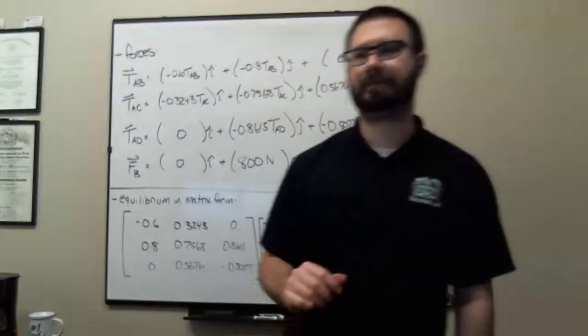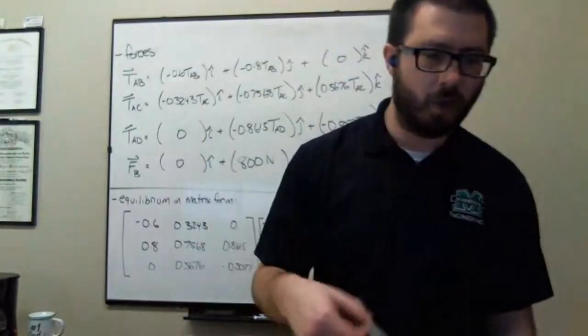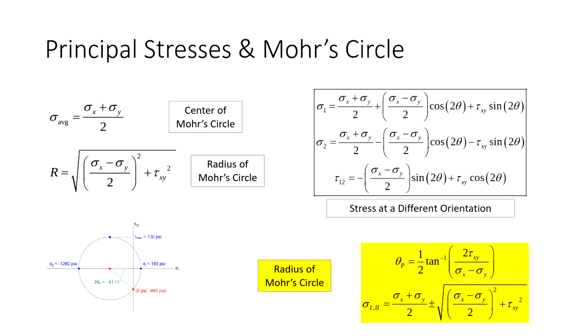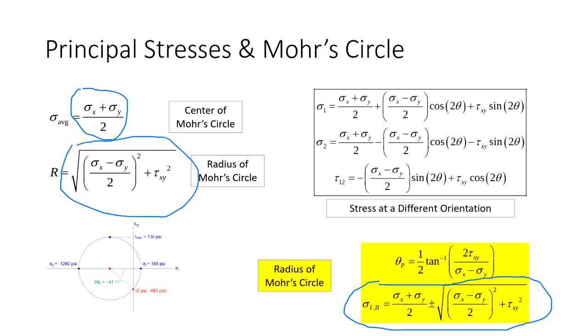If you look here, what we just determined was the maximum shear stress. If I said, no, I'm not interested in the maximum shear stress, give me the principal stresses. Again, they're just plug and chug, right? Right here. And this formula looks really fancy, but really all it is is the average stress plus or minus the radius, right?